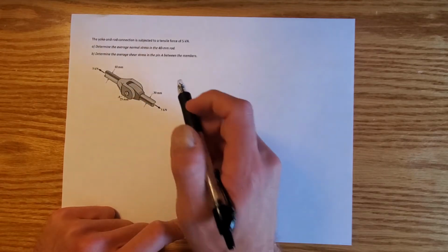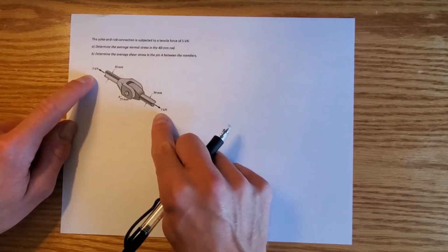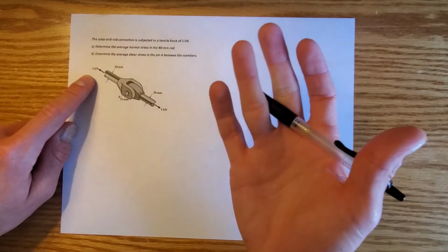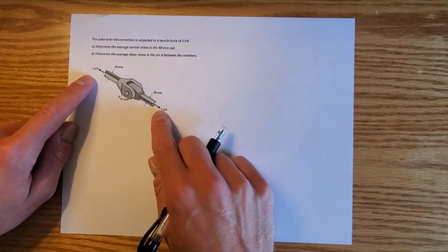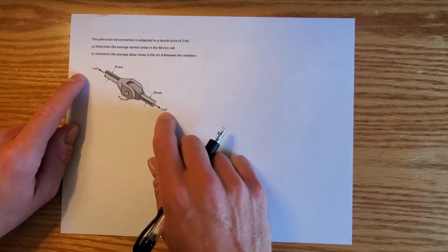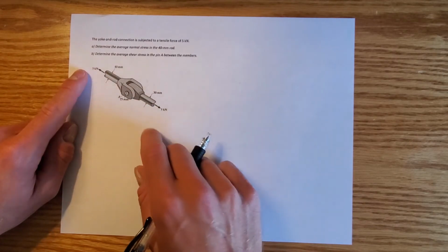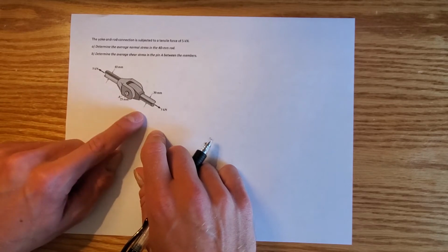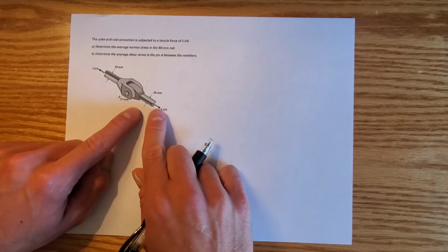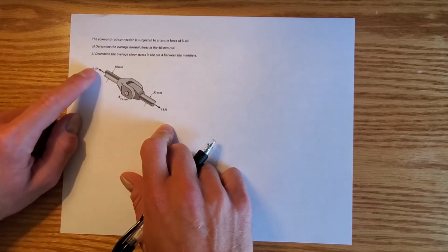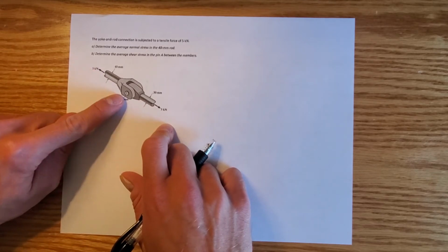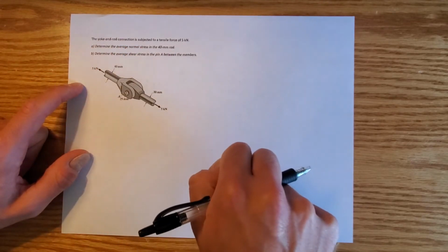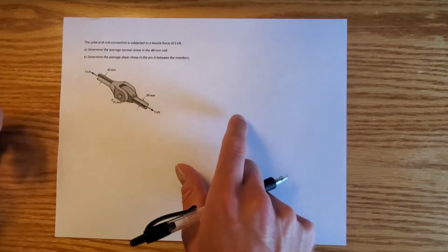Now something I always hear people get confused about is the fact that we've got a 5 kilonewton force on both sides. People think, wait, why is that not 10 kilonewtons of tension that this whole thing is experiencing if we have 5 and 5? Well, what's actually going on is that this is just a Newton's third law action-reaction pair. When you pull on this cable with 5 kilonewtons, as long as the other side doesn't move, it has to pull back with 5 kilonewtons. Therefore, someone's pulling with 5 kilonewtons this way, and the cable reacts accordingly.